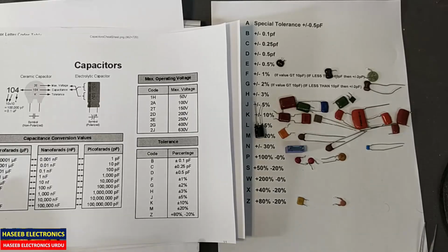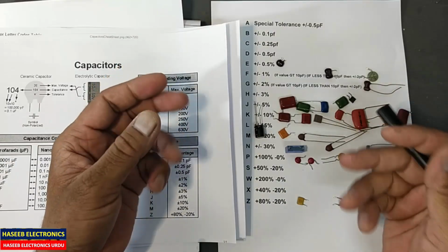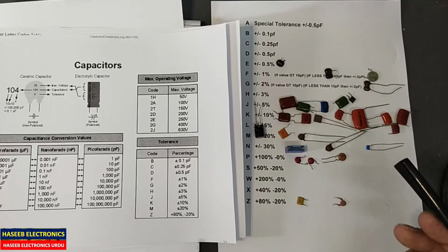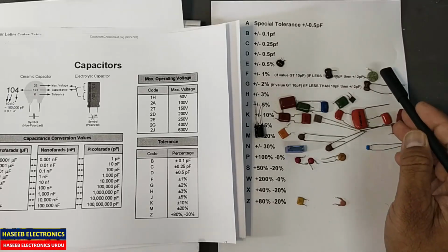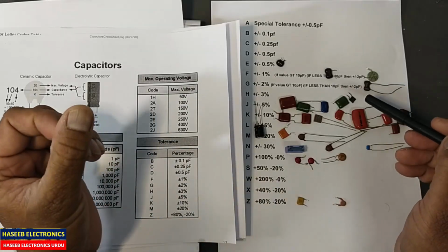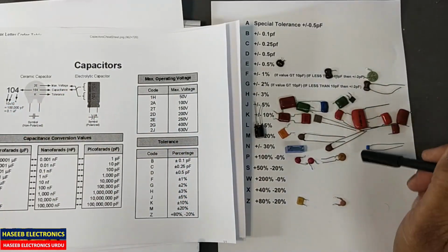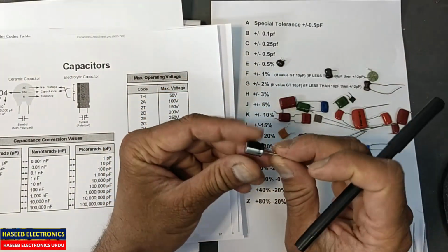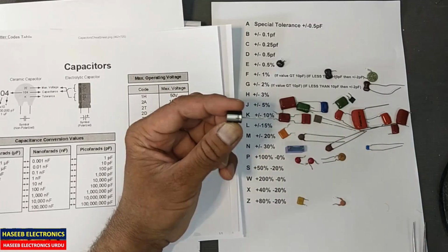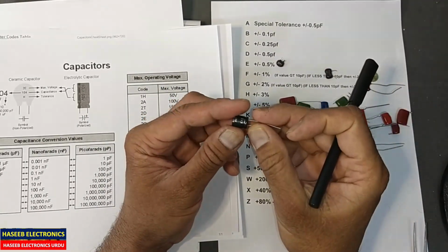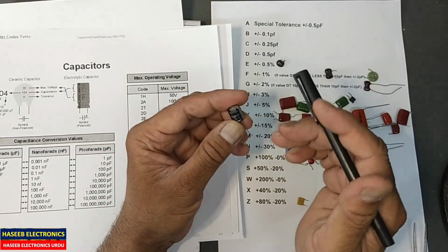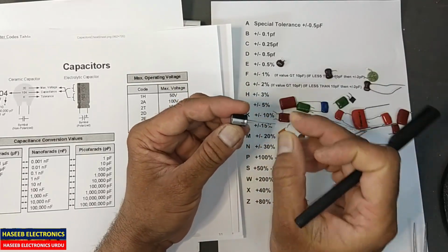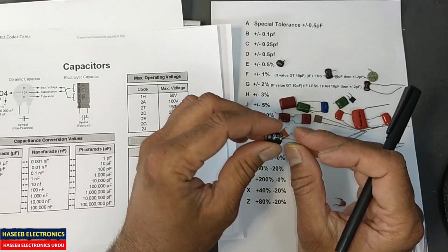In this session we will see that when we look at an electronics board, we see different types of capacitors with different colors, different sizes, and different packages. These are non-polar, non-polarized capacitors. We can say AC capacitors. When we see a polarized capacitor, that is a DC capacitor, it has some voltage rating, some capacitance rating, its manufacturer code, the series number, then temperature. It has polarity marking. So this is a polar capacitor.